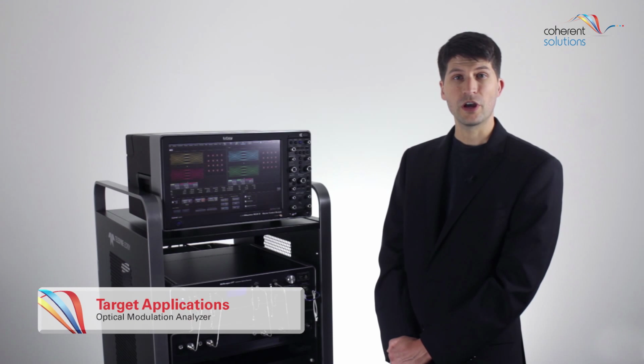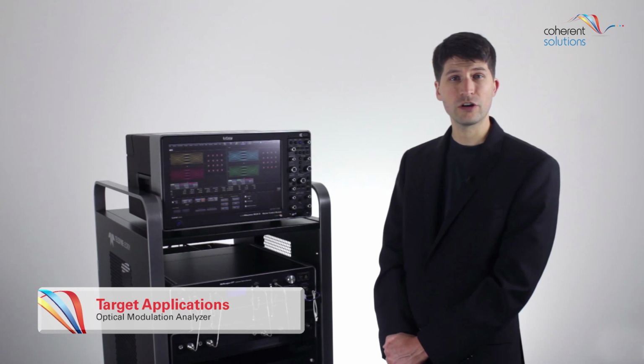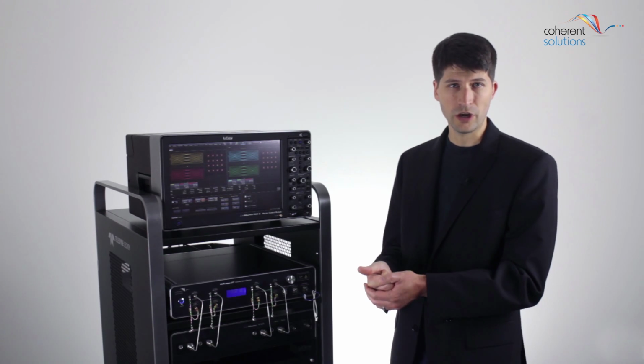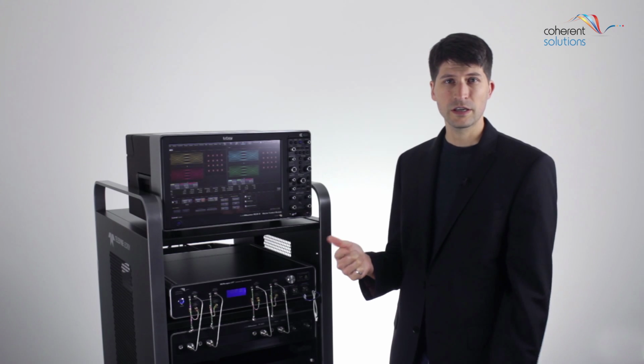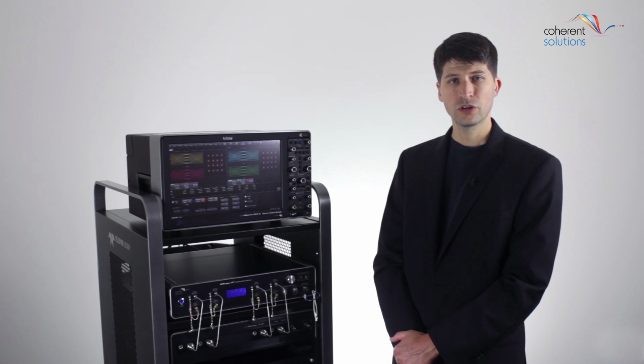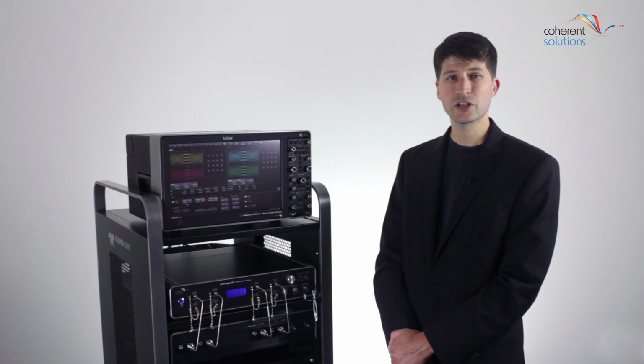So what's the purpose of an optical modulation analyzer? Well, there are 2 main applications. The first is to fully characterize your optical signal. So that's providing you information on the optical amplitude, phase, and the state of polarization for your signal. In this case, the Optical Modulation Analyzer is set up to manipulate your signal as little as possible in order to give you the most accurate representation of your optical electric field. This is the default configuration of the Optical Link software.